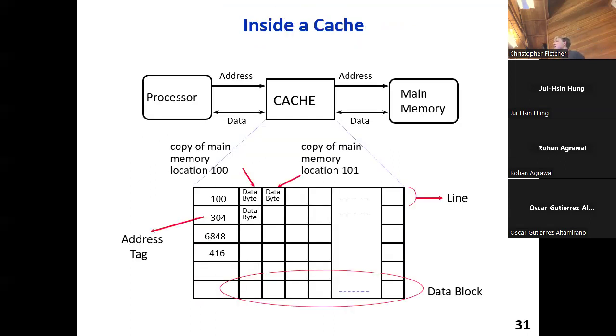At a very high level, a cache is an array built out of usually SRAM because it's closer to the CPU and therefore its capacity is smaller and we would like to be able to access it quickly. An array of data words that correspond to data that has been recently used, which means that it's going to be trying to exploit temporal locality, and coarsened into cache lines or cache blocks.